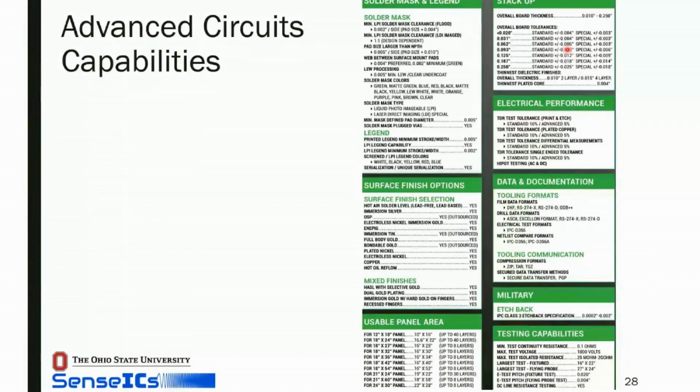So the answer was, does it impact the parasitics? Yes, certainly it could. Let's say, for example, you had 2 really tall pieces of copper next to each other. Yes, that would increase the sidewall capacitance. But I'm going to give you guys the answer why it's bad: it's actually harder for the PCB house to do the patterning. If you have really thick copper, it's harder for them to make fine features. Okay? So the features you can make are a function of the copper weight. And I think this was here, maybe I just glossed over it. But Mike, thanks for that.